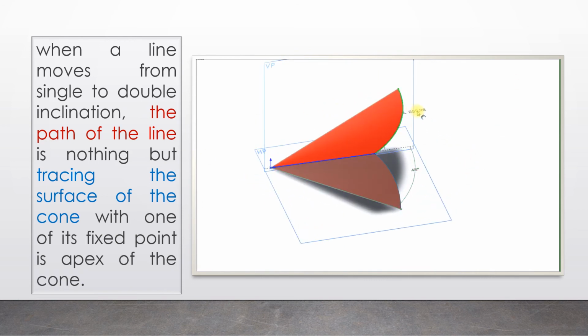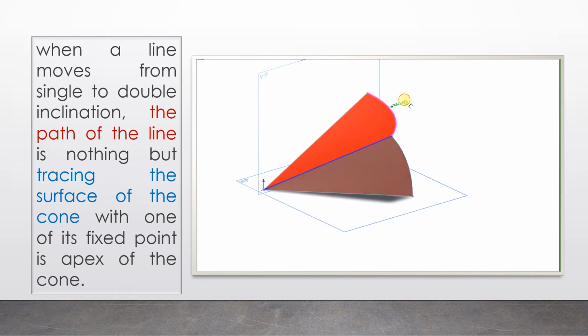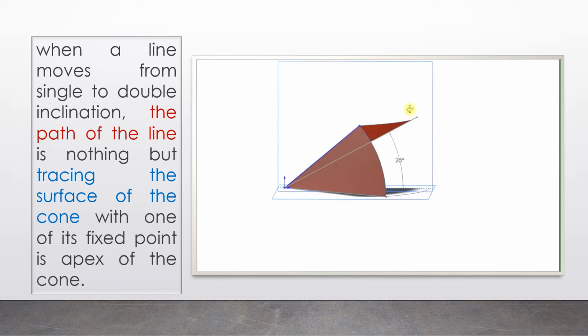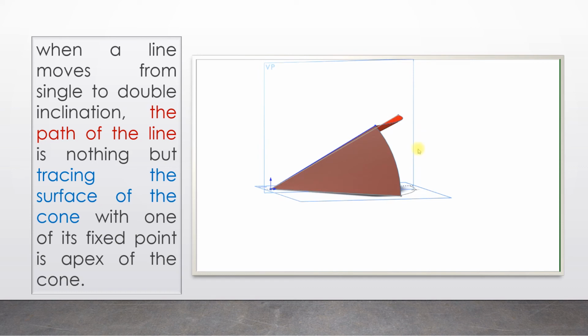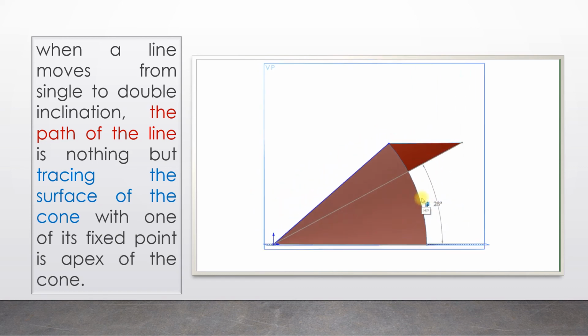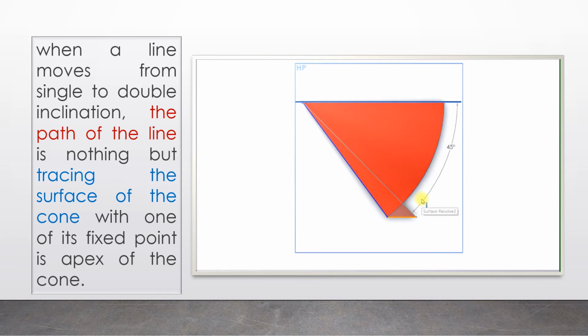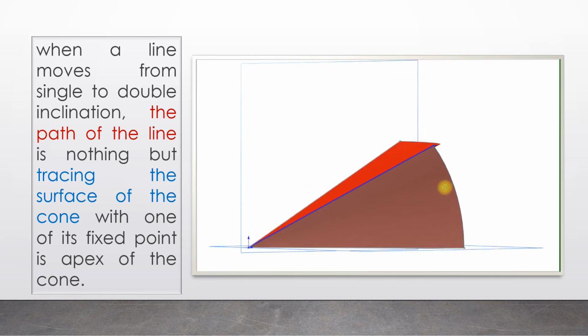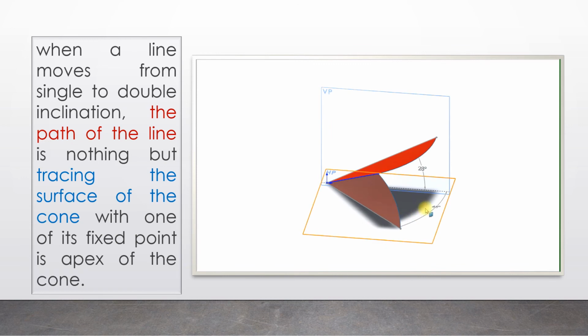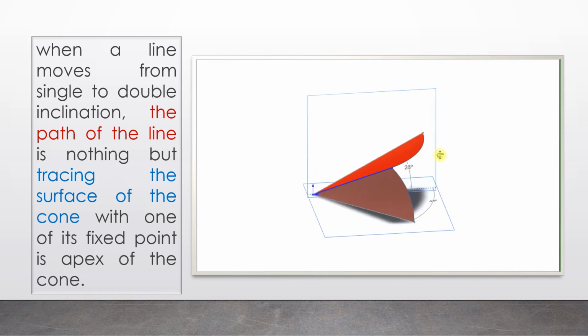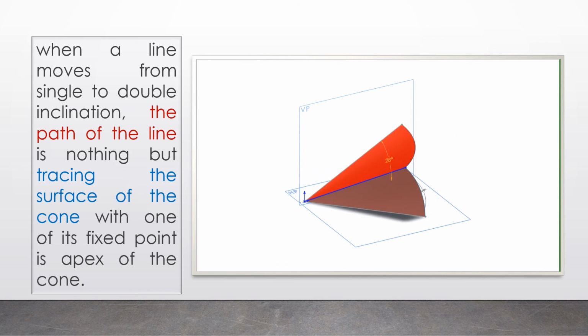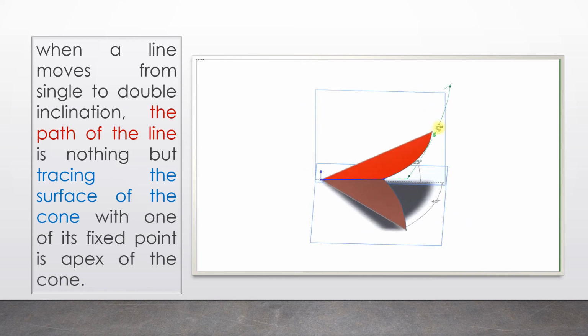But now look, a common generator. So the radius of this sector of the cone follows that projected length. Though we don't need it, we can see this visually only in this three-dimensional drawing. So when you look from the top, it's a straight line. Now see the angle between the common generator, which is the line inclined to both the planes, and the VP, that is 45 degrees, is visible. This can be visualized only in 3D.